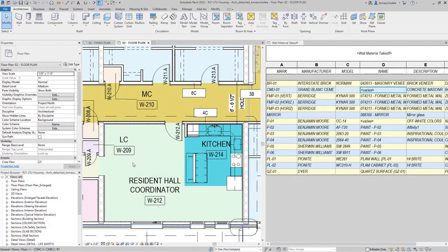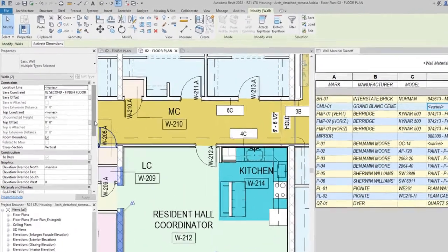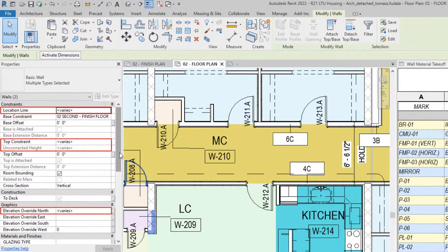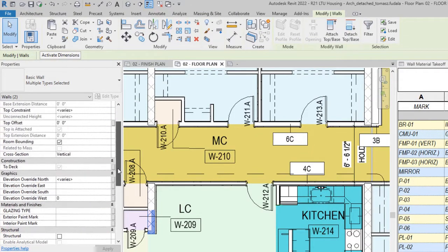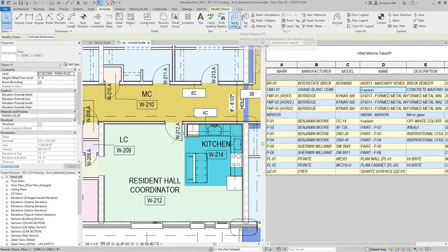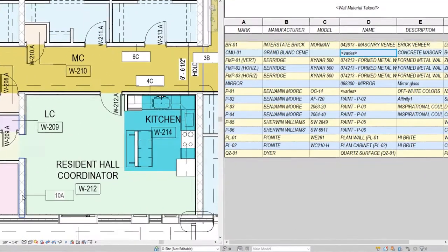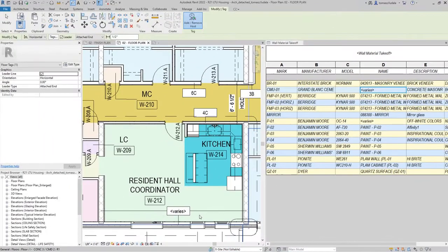In Revit 2022, you can control the display of properties when multiple elements having different parameter values for those properties are selected, scheduled, and tagged. When you select multiple elements, any properties that they share are reported. In past releases, if parameter values for the properties shared by the selected elements were the same, that value was reported. However, if the values differed, no value was shown.